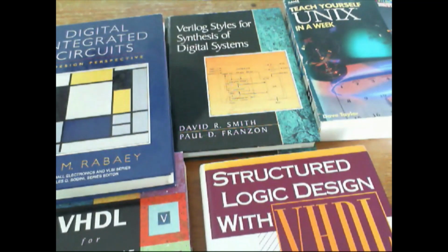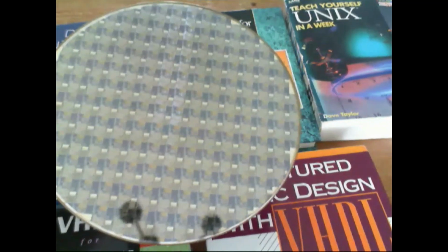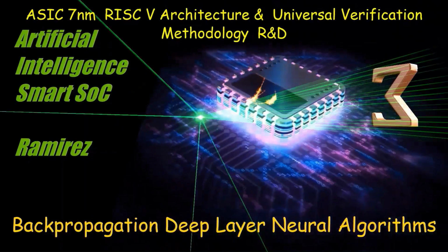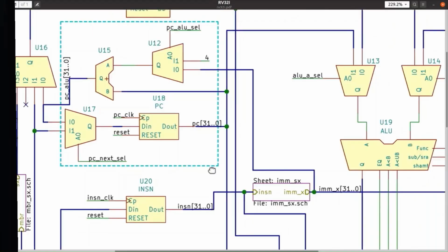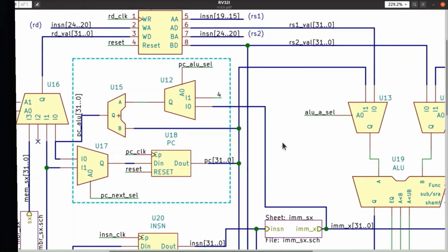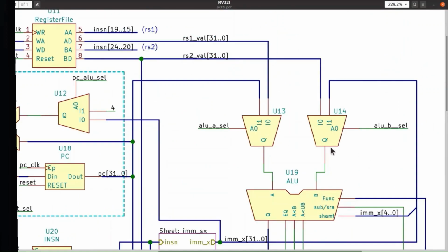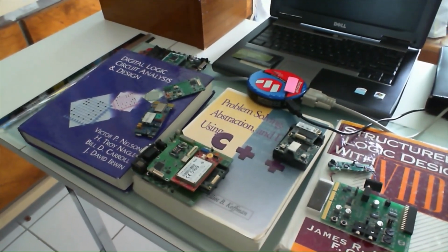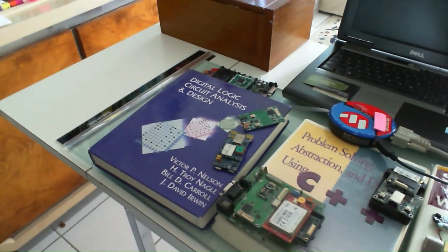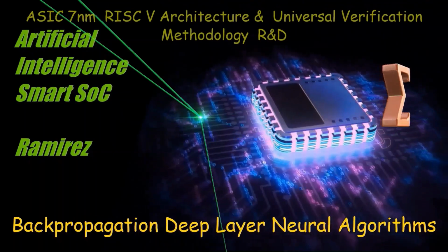For large macros such as multi-core embedded systems, where simulation speed in the system environment may be an issue, it can be useful to include cycle-based simulation and/or emulation models. In general, RTL that complies with the coding guidelines will work with cycle-based simulation and emulation. However, test benches and bus functional models, unless coded to the same RTL guidelines, are important and effective for large macros.